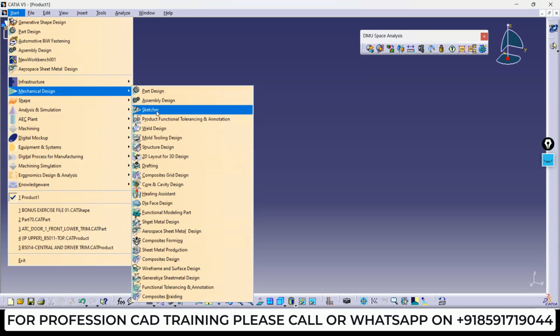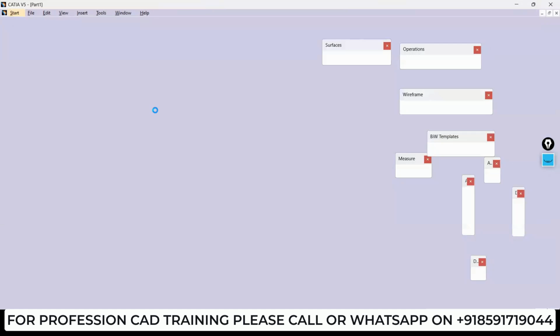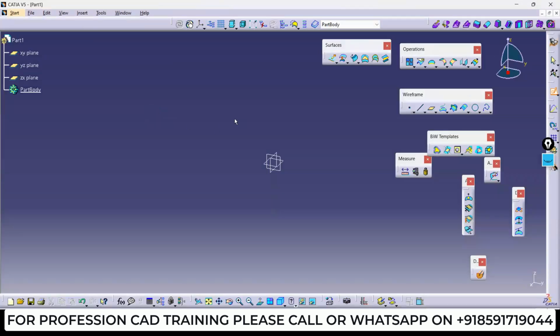workbenches. If you want to go to the Sketcher, you can simply click on Sketcher; if you want Part Design, you can go to Part Design. Once you click on the Sketcher, you directly cannot go into the Sketcher workbench. You can go via either Surfacing or Part Design. This is a Surfacing workbench; the last time I worked in Surfacing, that's why it is showing me the Surfacing workbench.